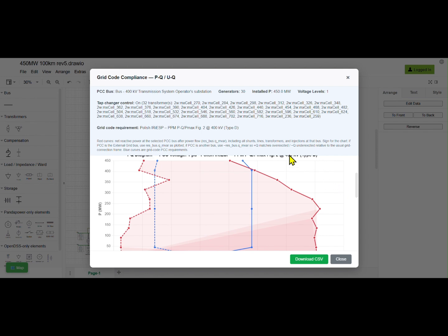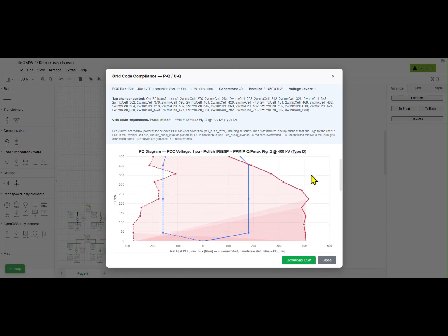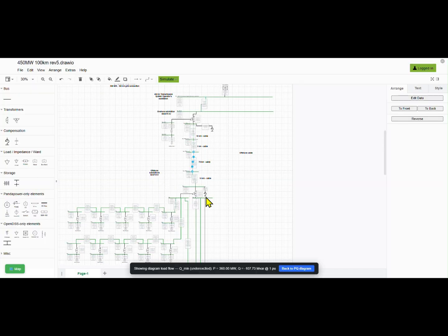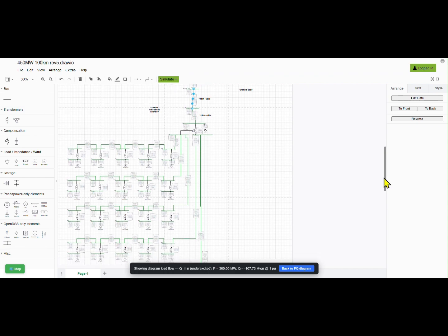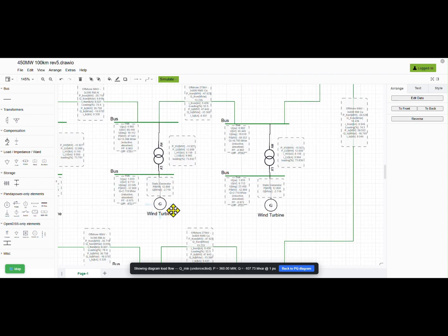Let's look at the result point of reactive power, which is minus 128 MVAR at the PCC. The active power is 225 megawatts. It was not computed at the generator's full underexcited capability. Each static generator is dispatched at minus 7.25 MVAR, equal to minus 14.5 times 0.5, i.e. only 50% of its Q absorbing capability.